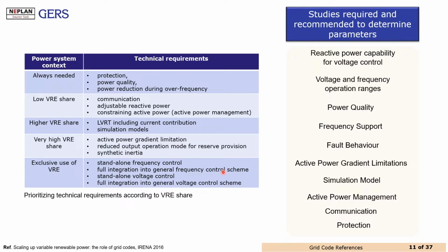The required simulations should consider power flow studies to research the reactive power needed to support the capabilities of the other generators. They need to identify different capabilities of the existing technologies to validate the potential capabilities and lower cost. Static and dynamic simulations are required to validate the protection settings and low voltage ride-through requirements.